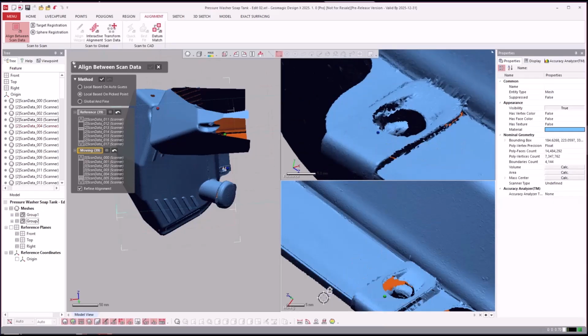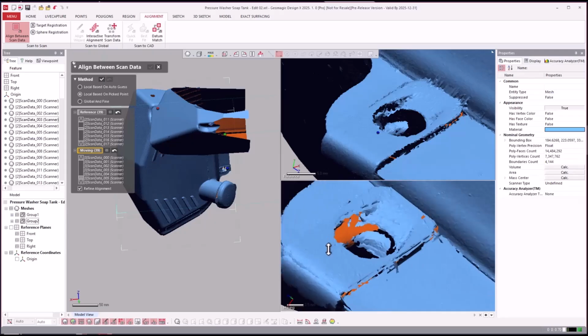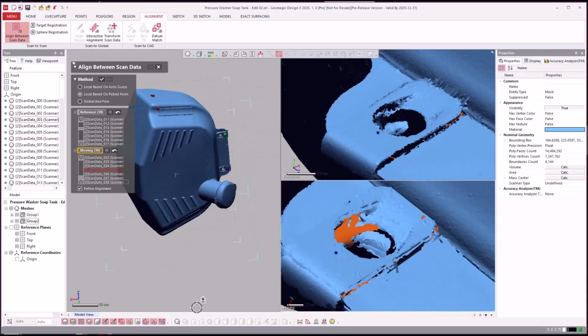It does help sometimes to find little monuments somewhere to help you select an area. And you see here, it's close enough. I use 3, and then I can go ahead and hit the checkbox here, and it will then do the best fit. But you notice I didn't hit the box up here. I just want to run the alignment right here first, and then I'm going to switch over to global fine, or global and fine, and run that before I get out of this command. I want to do a fine adjustments best fit afterwards that uses a little more of the data.